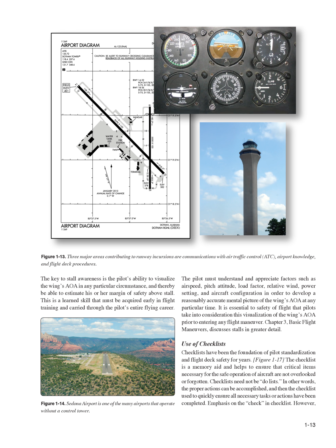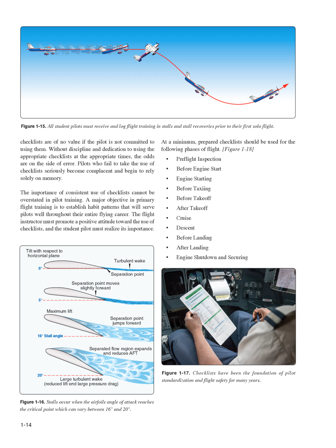Emphasis on the checklist. However, at a minimum, prepared checklists should be used for the following phases of flight. Figure 118. Checklists are of no value if the pilot is not committed to using them. Without discipline and dedication to using the appropriate checklists at the appropriate times, the odds are on the side of error. Pilots who fail to take the use of checklists seriously become complacent and begin to rely solely on memory. The importance of consistent use of checklists cannot be overstated in pilot training.